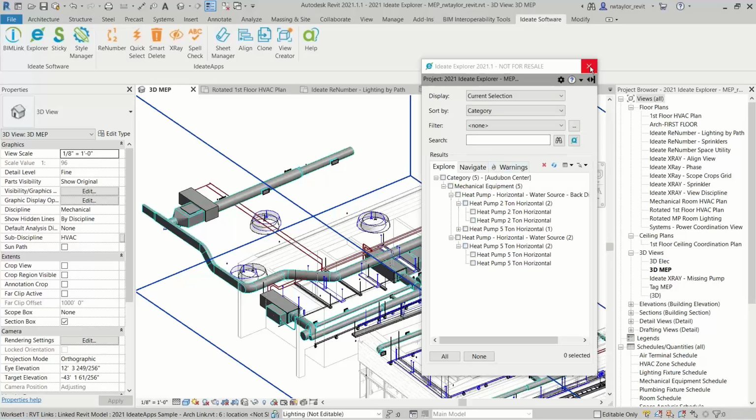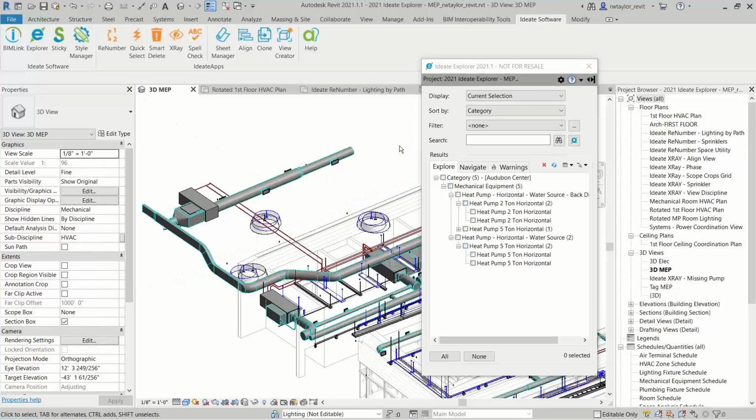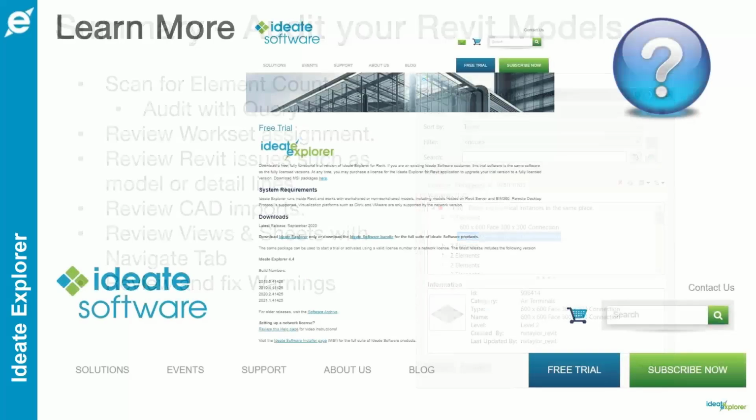Yep. It's very much the same situation as in AutoCAD. If you brought in a block or did an XREF and you exploded it, even if you delete all the actual content from the drawing, the residual data like the extra layers and any other additional styles that came in are still there, and that's where Style Manager can come in and help you clean that up.